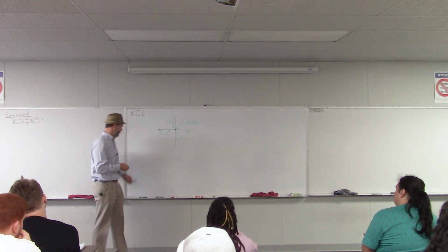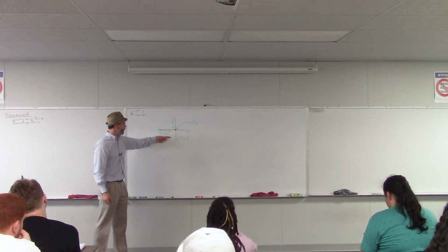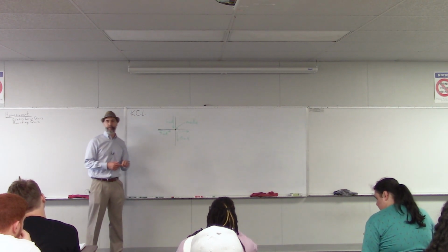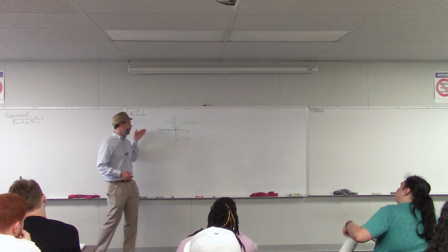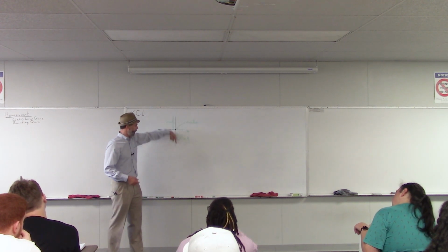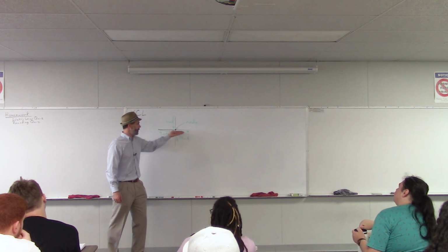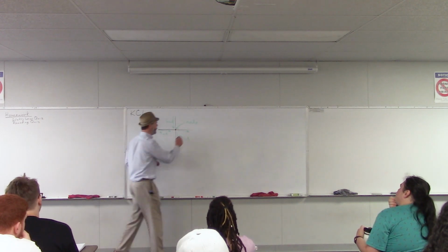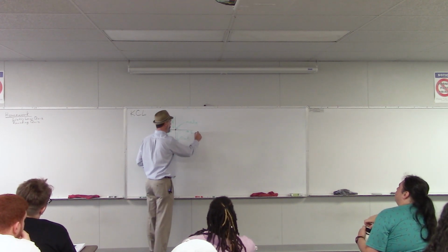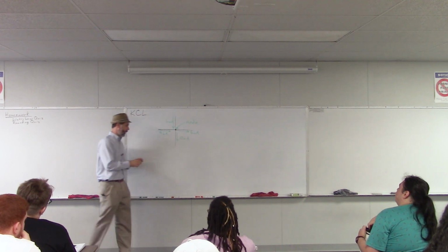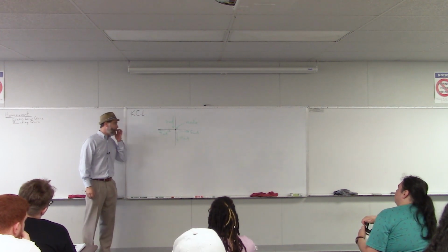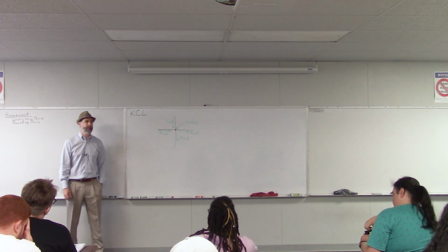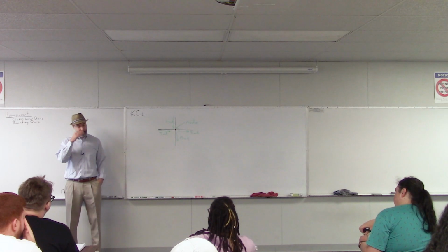Well, let's see. So we've got 9 flowing in and 6 flowing in. So how much is that altogether flowing in? 15, right. So we got 15 milliamps flowing in, and then 10 of that flows out down this way. So whatever's left over has to flow out that way. So how much is left? 5. 5, that's right. So we would have 5 milliamps flowing out that way, okay? So that's what Kirchhoff's current law says. Any questions about that? Could you do like one more example?